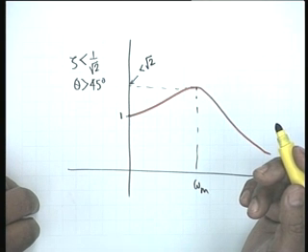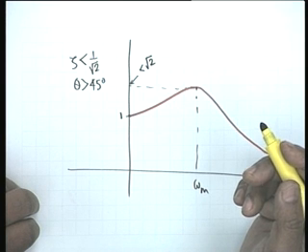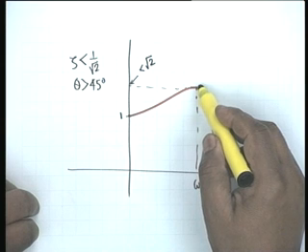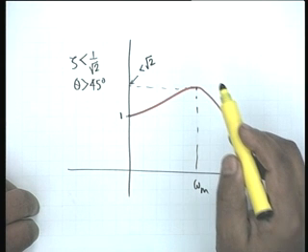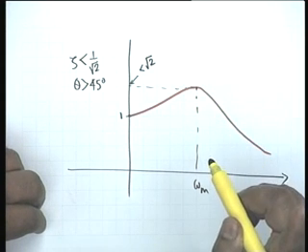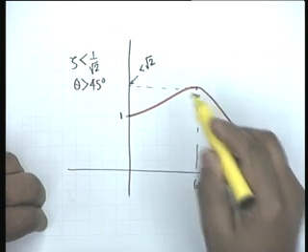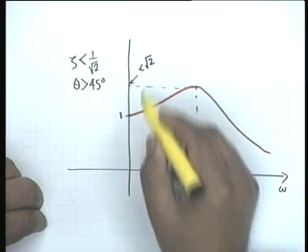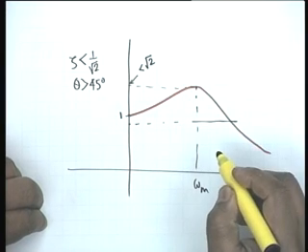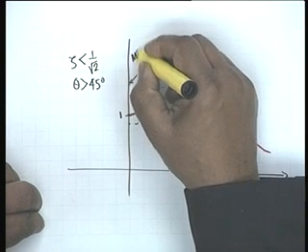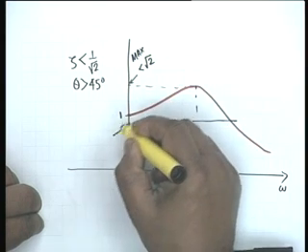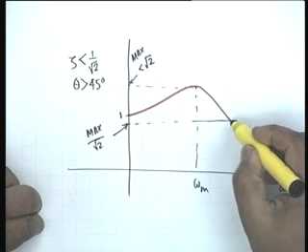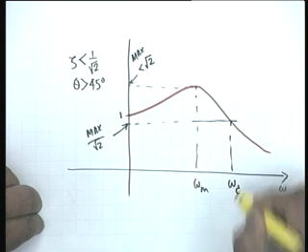All right, then obviously 70.7% down from this value shall occur only at one frequency. If the maximum is less than 1 by root 2, then 1 by root 2 times this will be somewhere here. Let us call it max, max less than 1 by root 2, and this max by root 2 shall occur only at one frequency, and this is omega c.